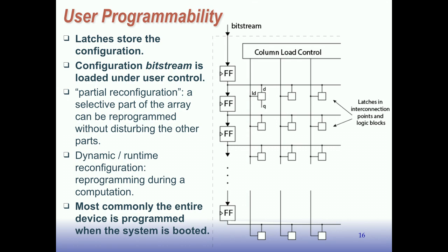Most commonly, though, the entire device is programmed when the system is booted, as I mentioned. So the board will be booted, and then all the bits will come in through the control of a microprocessor or some flash memory and program the whole FPGA. And then it'll be ready to go. There'll usually be a reset sequence to reset all the flip-flops and all the state.